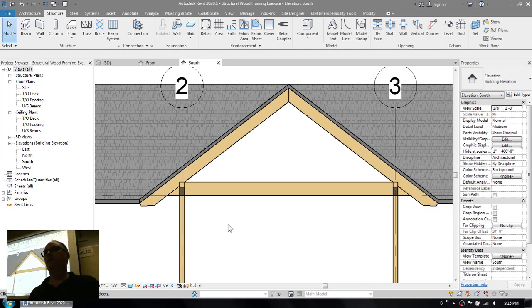So when I'm building expressive structure like this, often it's based on 2 things. We have a roof with a given slope. So we've got a roof design that we've built. And what we want to do is build the structure that's necessary to support this roof. So it's a wood deck, a decking style roof with the little flanges that interlock. Those are going to be built sitting on top of these rafters. So these are, I guess, purlins, you might say.